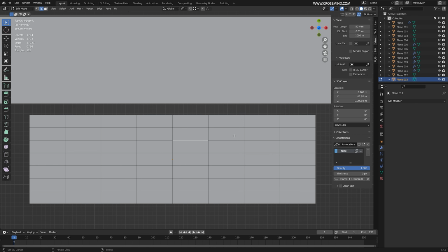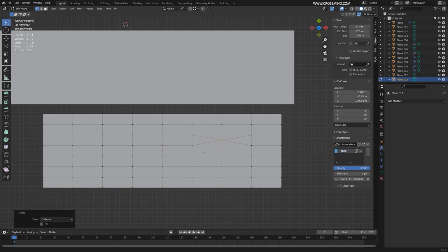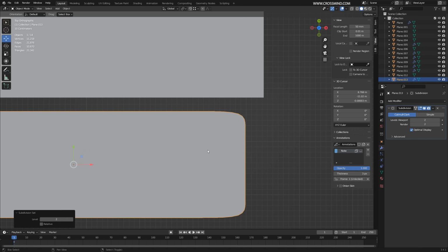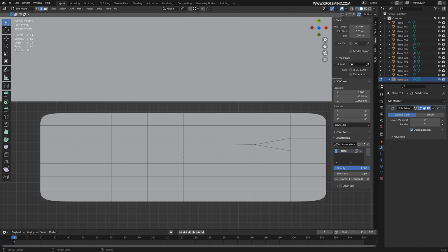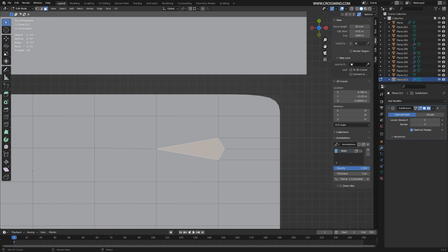Or in other situations where you need to collapse the entire row of such vertices, you can simply collapse two of these. Then you can get rid of this entire thing. And now you got rid of one of the loops here, but then you have one triangle here. So to solve this, just add one right here. So this is a quad now, and these around the center one are also quads. So this kind of makes a diamond shape. It's also useful in a few scenarios.